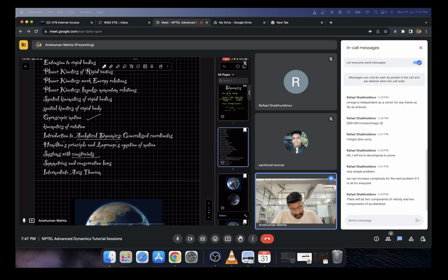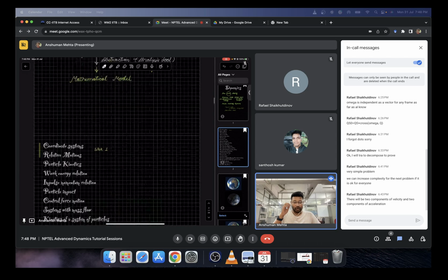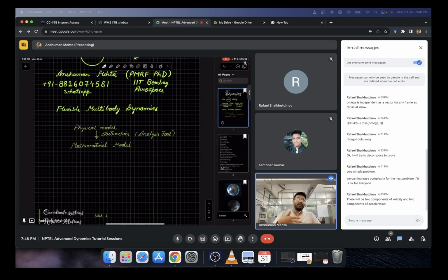And yeah, the next thing which introduces complexity is constraint. Now constraint is something which we take very lightly. It's like, okay, this is constrained to that, but actually if you look into analytical dynamics, you are making a mathematical model out of it. Now you have to provide what the constraints are, you have to provide what the degrees of freedom are. How will you know that degrees of freedom are independent of each other, if something is not affecting the other? For that you have to use something called Lagrange multipliers.